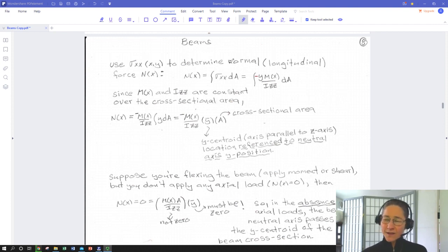Okay, one thing that we did mention in passing was the potential effect of a direct applied axial stretch, as opposed to the forces and stresses that come from flexing the beam. So we can either grab a beam and just stretch it, or we can keep the end supports the same distance and just flex it. That would correspond to our N, capital N, internal force, meaning a normal force, normal to our cross section, or M, the flexion.